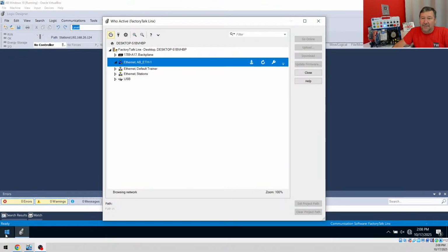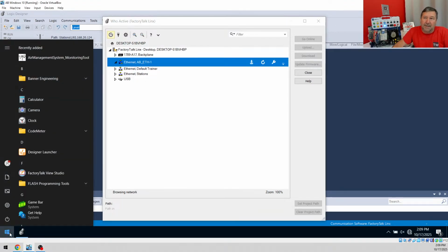And what I do, if you're in our class, then we have a very basic step guide, and that's what I'm going to walk you through here of how we can troubleshoot our network connections. First, now we know the IP address of our PLC. We're going to see if it's out on the network. And to do that, we're going to go to the command prompt.